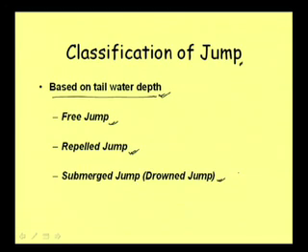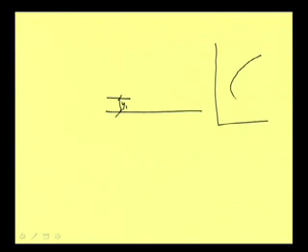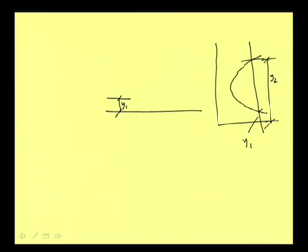Let us see how this tailwater depth is significant and how it influences the hydraulic jump. Say we have a y1 here. Now, let us refer to the specific force diagram. This is the specific force diagram and this is y1. This is y2. Specific force F is on this side, and on this side we are putting the depth y. Sequent depths mean this y1 and y2.